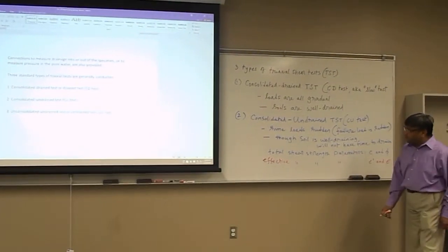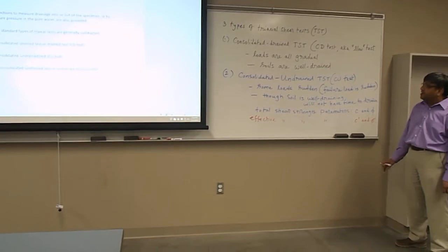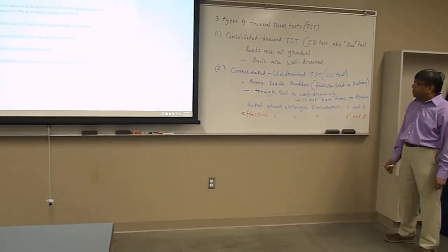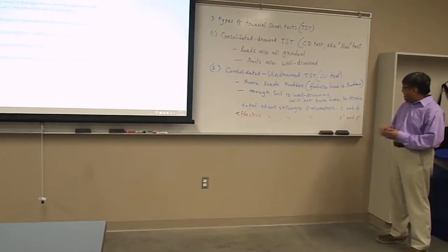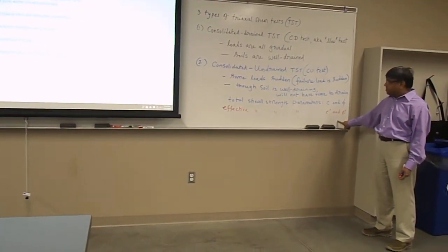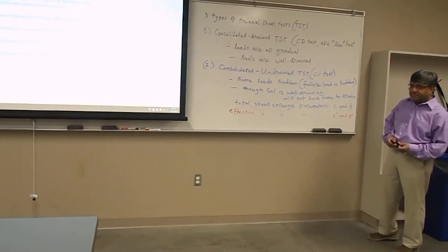In this test, we measure the pore water pressure and use it to calculate the effective stresses, and then plot the Mohr circles or use equation 10(9) to get these two sets of parameters.